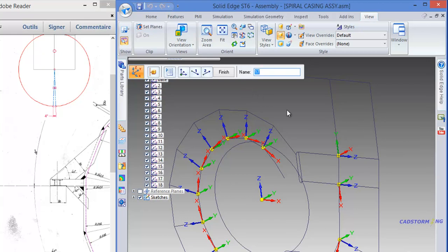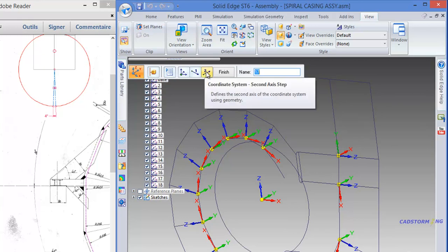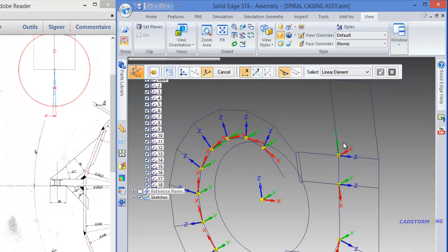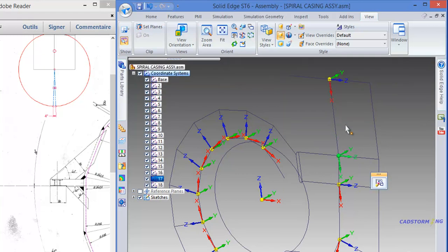Click on it, and the z-axis, which is my first selection, is okay, but the y-axis is not in the right position, so it is the second step. Instead of the x-axis being normal to the sketch plane, I want the y-axis, so I will select this option, and then again planar face, select the plane, right click, choose the orientation, and there it is, finish.